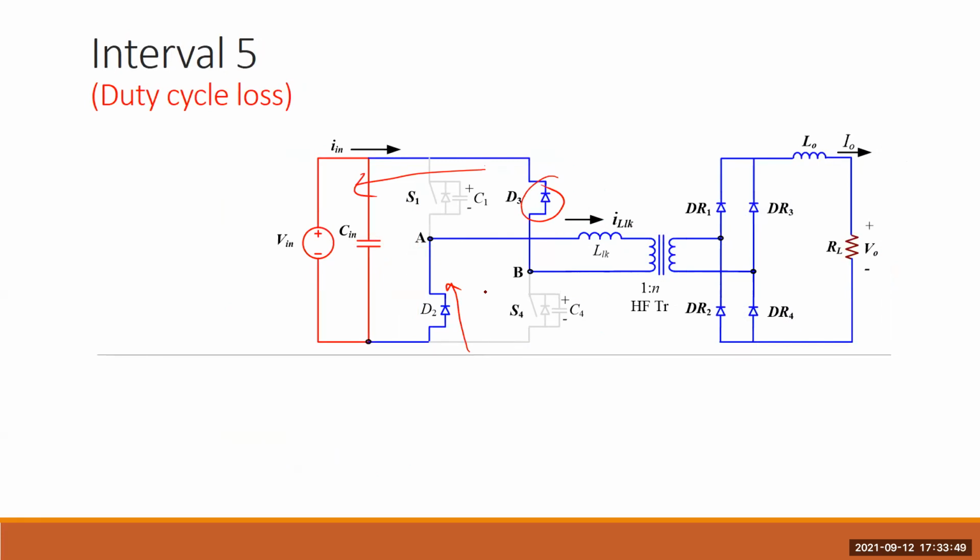So overall you can get a similar efficiency compared to the duty cycle modulation. The energy that was in the snubber capacitor is just going back to the source rather than dissipating immediately in the switch by hard switching.